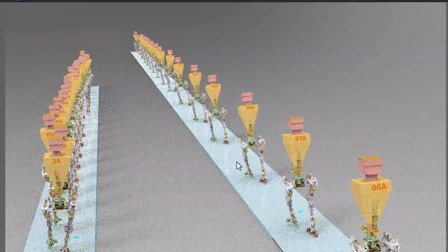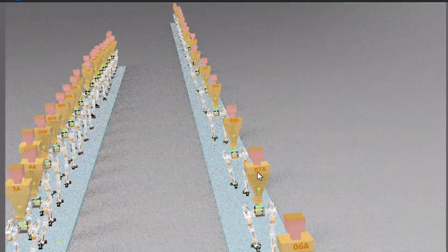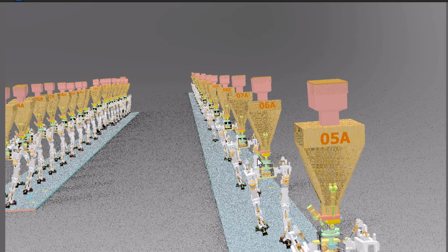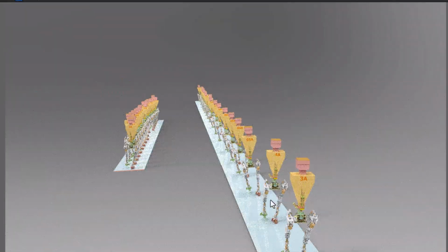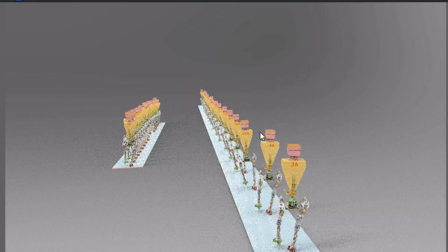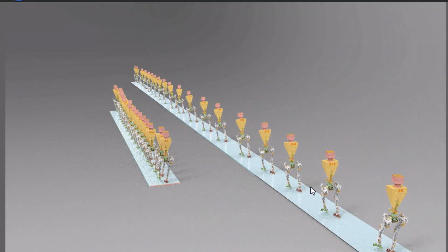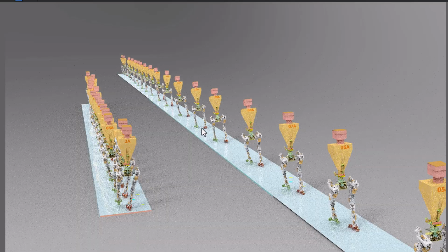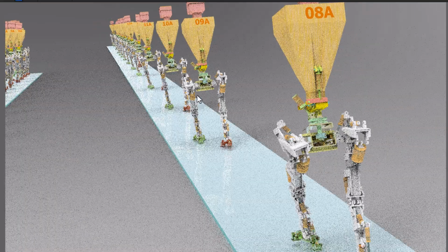I remember I had the stances of the robot and I spaced them out so we could get behind it and notice what's happening as the robot switches its weight from one leg. You'll see how it's kind of tilted off to the right. And in order to move up the right leg, it has to, what I call, unweight it. And so in order to do that, it has to get its left foot on the ground, holding up the weight of the robot.